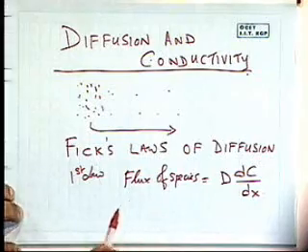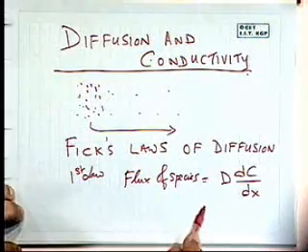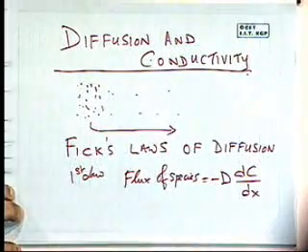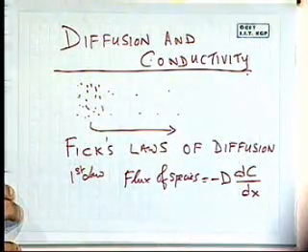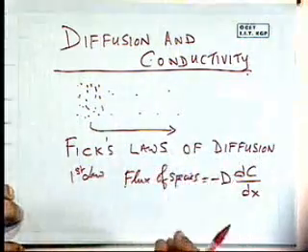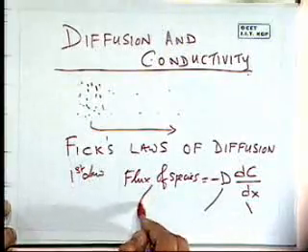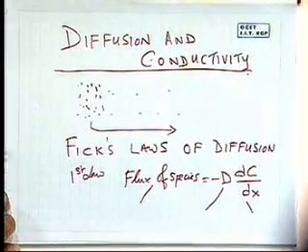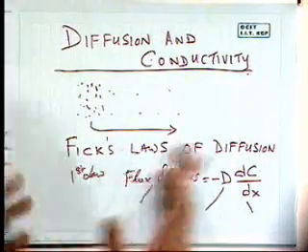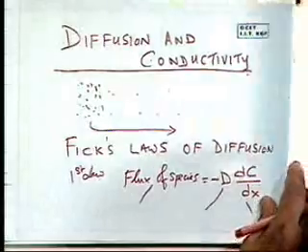And because the flux will be in the direction from the higher concentration to the lower concentration, there is a negative sign to indicate that. Okay? This is the basic Fick's first law. And we'll make use of this, the diffusion coefficient, the concentration gradient, and the flux of the species to try to arrive at what will be the diffusion current if we have such a gradient in the electron concentration or in the hole concentration.